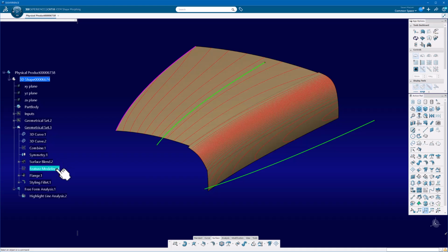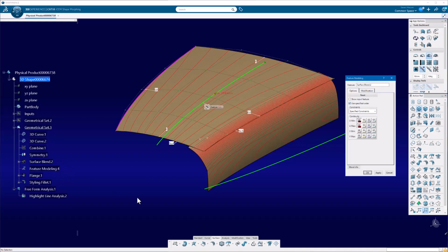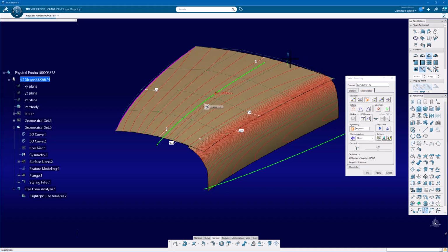Because if I go back in here and double click on that feature, I'm going back to that original, right? I'm not modifying it again. I'm remodifying it, right? I forget all the time to apply my symmetry plane, as I'm so used to stuff like this. And because it's applied as a feature, it remembers the symmetry plane. It remembers the modifications that you've already done, right?